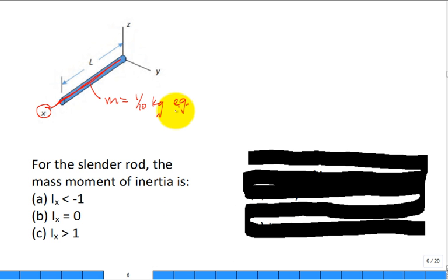All right. So if I think back to it, it's our inertia. It's mass moment of inertia. It's the sluggishness with which something accelerates angularly. So if I say I sub x, each one of these has x, right? It's the integral of, if I looked at maybe the y-z plane, it would be around this point, which is the origin, and the equation that would make sense is r squared dm.